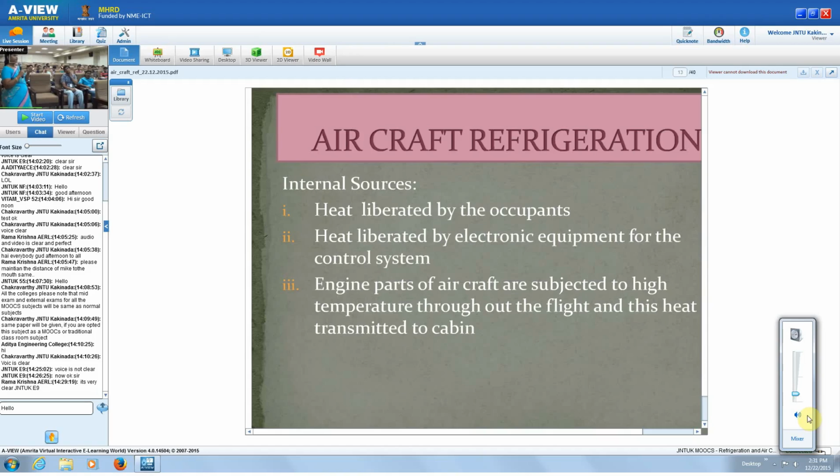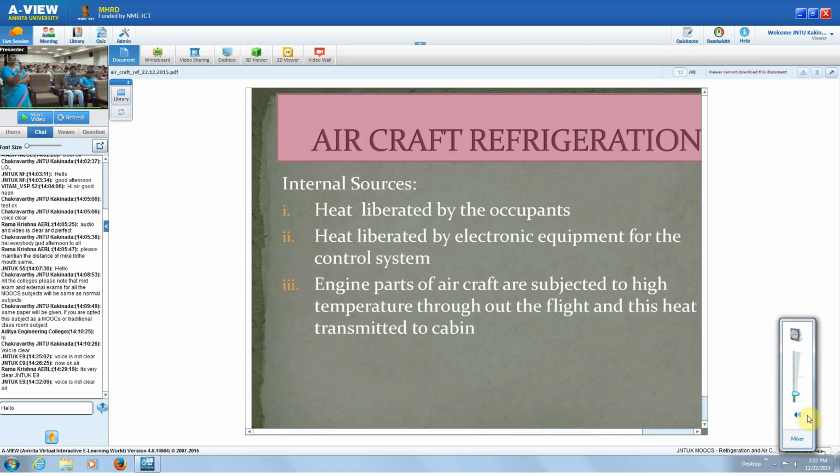In the compressor, the air is compressed and afterwards heat is added in the combustion chamber. Then the gas is at high pressure and temperature. When it is expanded through a turbine, we get some work. Nearly all the work done by the turbine is utilized for running the compressor only.